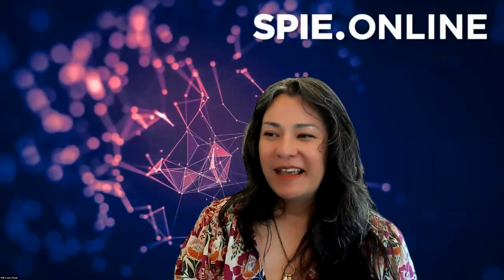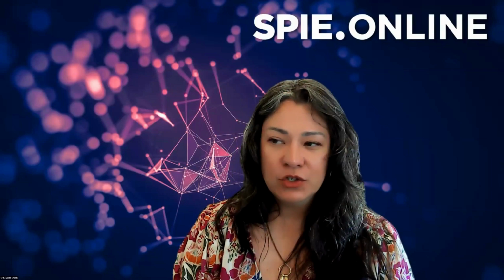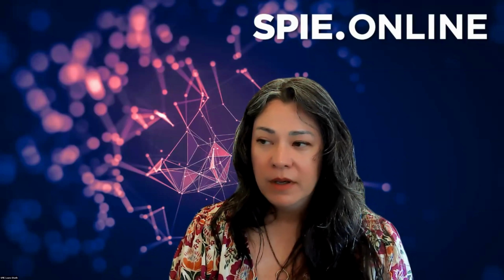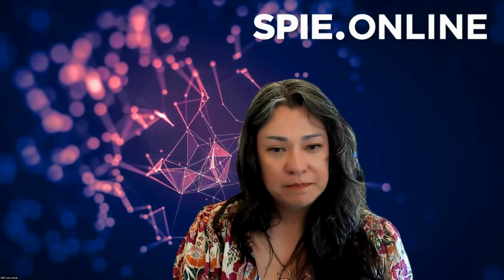We have another one from Alexander Lin. The comment in the Q&A is that lens shading correction corrects for the relative irradiance falloff from the optical system, and flat fielding can be used to correct for sensor non-uniformity. Is there a way to correct for vignetting? Well, the vignetting and the optical roll-off are kind of similar. I kind of think of them as really the same thing, but a difference in degree.